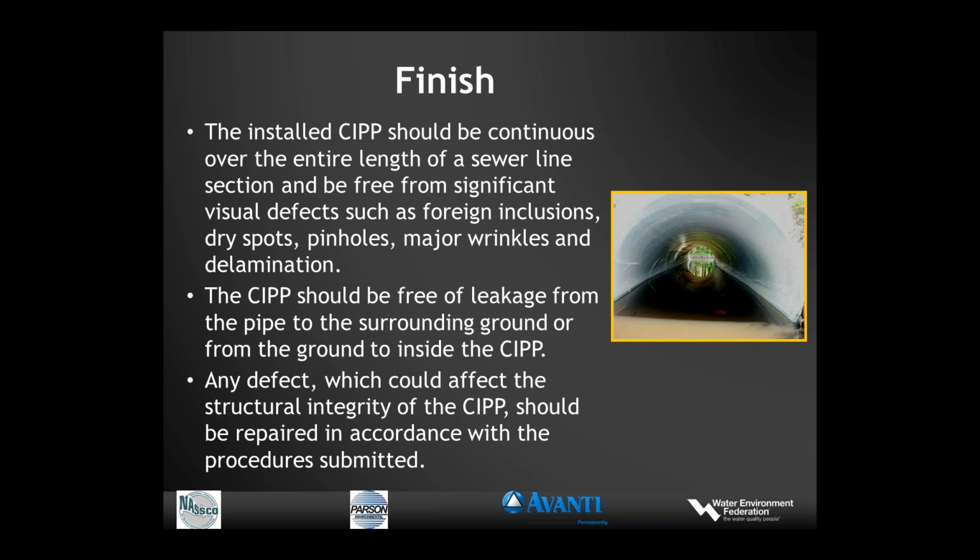The CIPP should be free of leakage, either out of the cured-in-place pipe into the ground, or the groundwater shouldn't be leaking in. And any defect which will affect the structural integrity or the longevity of the CIPP should be repaired, and the method of repair would be in accordance with those procedures previously submitted.